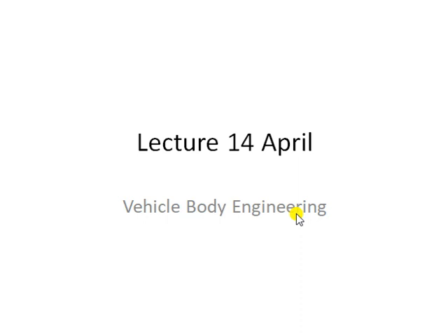Unit 4 was basically about the discussion of a few load cases, or load cases means a few loads which are acting on the vehicle in different conditions, like in the static condition, in dynamic condition, while traveling straight on a path, while taking a turn, while accelerating, while braking, while moving up on a hill, while moving down on a hill. During these conditions, different forces are acting on the vehicle body, and in this unit we tried to analytically calculate the different forces, their magnitude and direction, and how these forces may affect the overall functioning of the vehicle. That we discussed in Unit number 4.